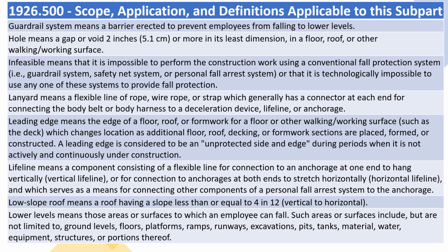Lifeline means a component consisting of a flexible line for connection to an anchorage at one end to hang vertically, vertical lifeline, or for connection to anchorages at both ends to stretch horizontally, horizontal lifeline, and which serves as a means for connecting other components of a personal fall arrest system to the anchorage. Low slope roof means a roof having a slope less than or equal to 4 in 12, vertical to horizontal. Lower levels means those areas or surfaces to which an employee can fall. Such areas or surfaces include, but are not limited to, ground levels, floors, platforms, ramps, runways, excavations, pits, tanks, material, water, equipment, structures, or portions thereof.